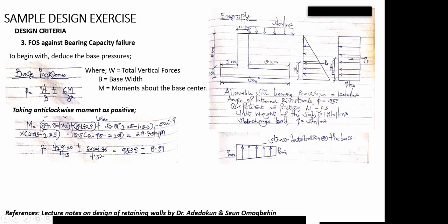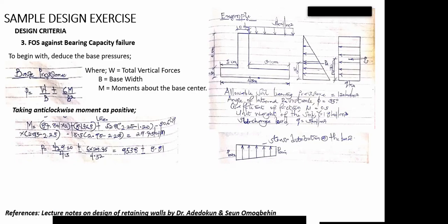Don't forget we've taken the horizontal component of our earth material. Now let's take the vertical component of our earth material, which is 306.9. We generated that by using area multiplied by unit weight earlier. So the 306.9, don't forget, this is where your soil is acting. Because your soil is acting here, the vertical weight of that soil will be at the center of 3.1.